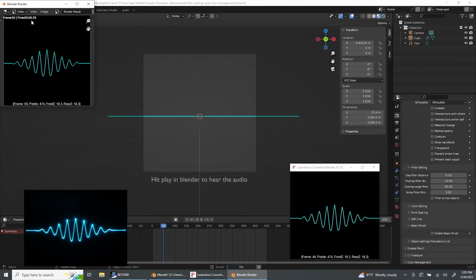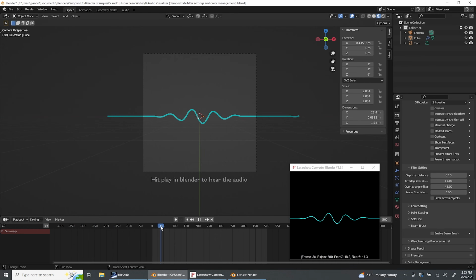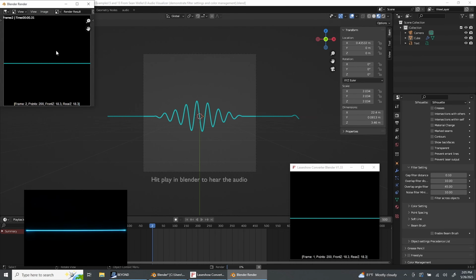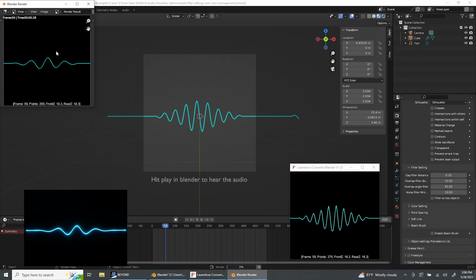But the result isn't perfect, because in addition to having our single line, sometimes when the angle becomes too sharp, it's not really an overlap, but we get these short little peaks out here, and we'll use what we call the noise filter, the thing that strips out short little peaks. And we say if anything's shorter than 10 beam diameters, just get rid of it. We'll take a look at that. So now you can see that we have our single line with no additional short little lines up top. So that's worked out pretty well. Nevertheless, can it be made better?